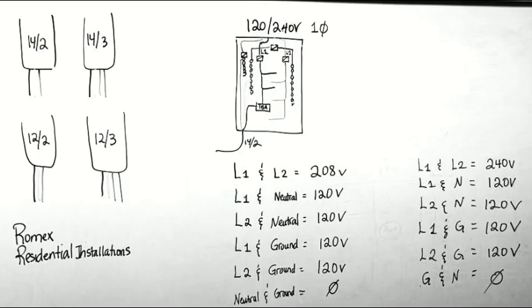It has to pass through resistor number 1 and pass through resistor number 2 and pass through resistor number 3 to be able to get back to that power source. Current has only one path to travel when we're wiring in series. Now this is the reason why we don't wire homes in series. We wire homes in parallel because in this type of circuit, if one of the resistors fails, what do we have there? What do you see there? We have an open circuit, correct? So this would be an open circuit.